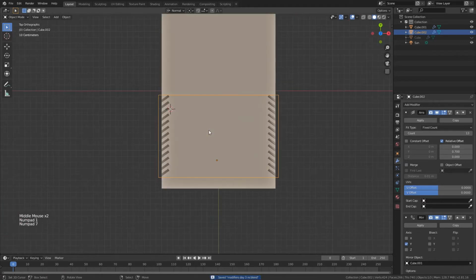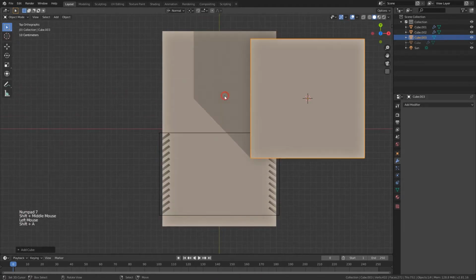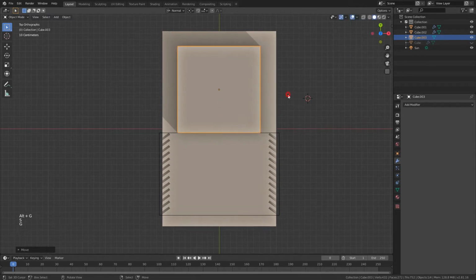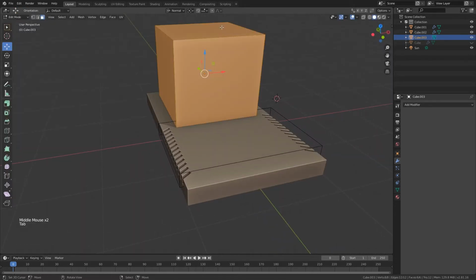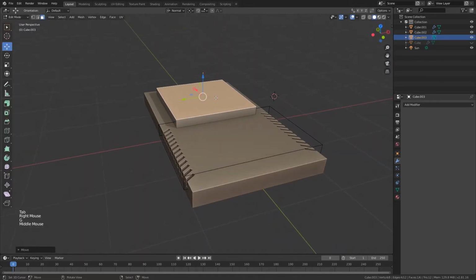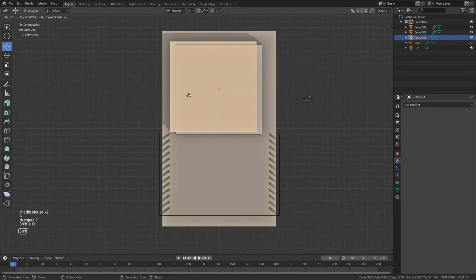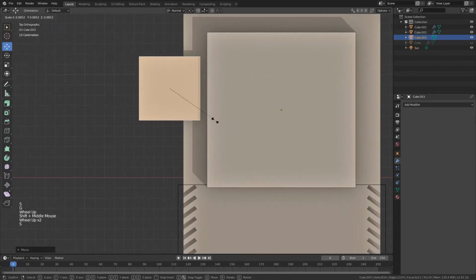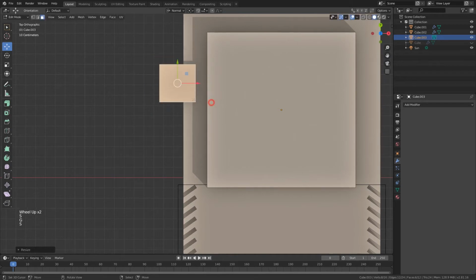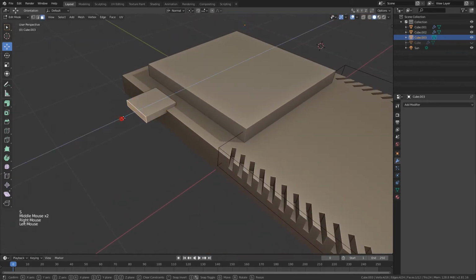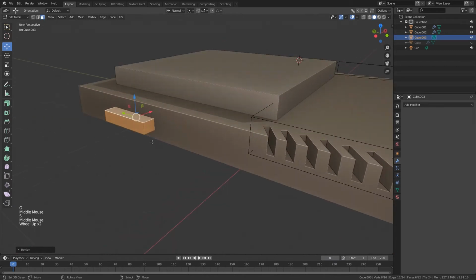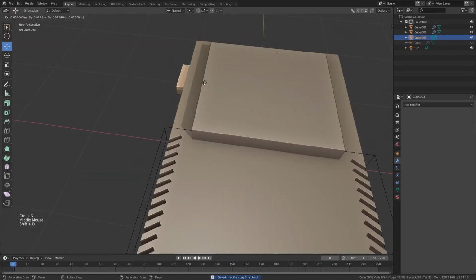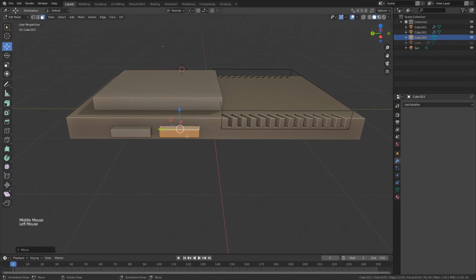you can clearly understand what the benefit of working with modifiers is. Now let's go to top view and bring a cube over here and place it right here, and I can maybe make it not so tall, and I can create a duplicate of this in edit mode. Now I'm creating the duplicate in edit mode so that I don't have to apply too many boolean modifiers, and I can work with only one, and these two are one object for now. Okay, I'll place it over here, and I can make a duplicate of this again and make another button over here.